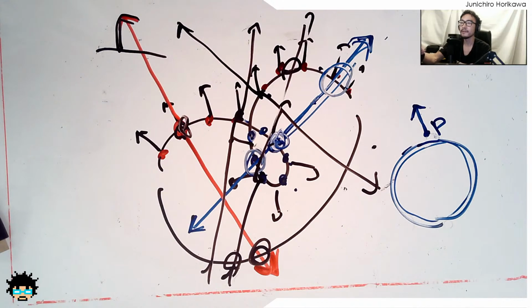If you have bigger geometries, like if the default size is 1000, then you want to make it like 10,000 or something. But for now, the size of the sphere is 1, so using 1000 is good enough, right? And as a result, you'll get P1, U, and V. Right, so that's one intersection going from the point position outward. Now you also want to check the inward intersection. So let's name this 2, and for this one I'm going to use the same starting point with a little bit of offset, then also a negative N, which is going to be an inward ray.